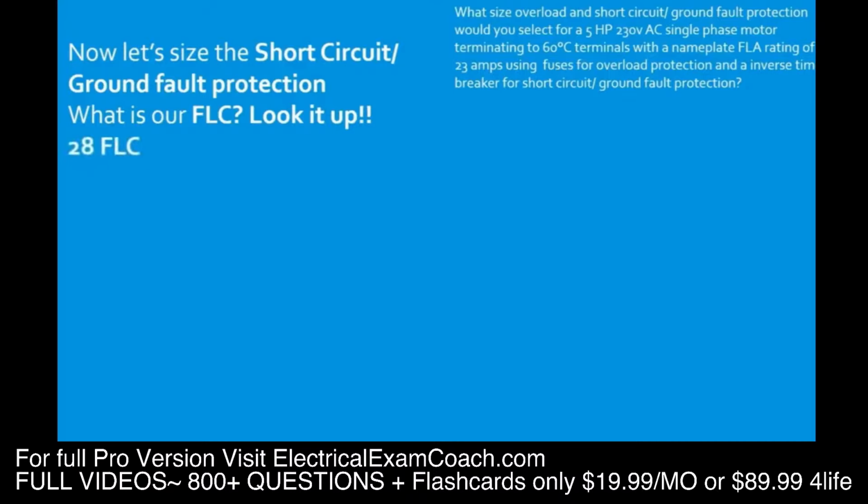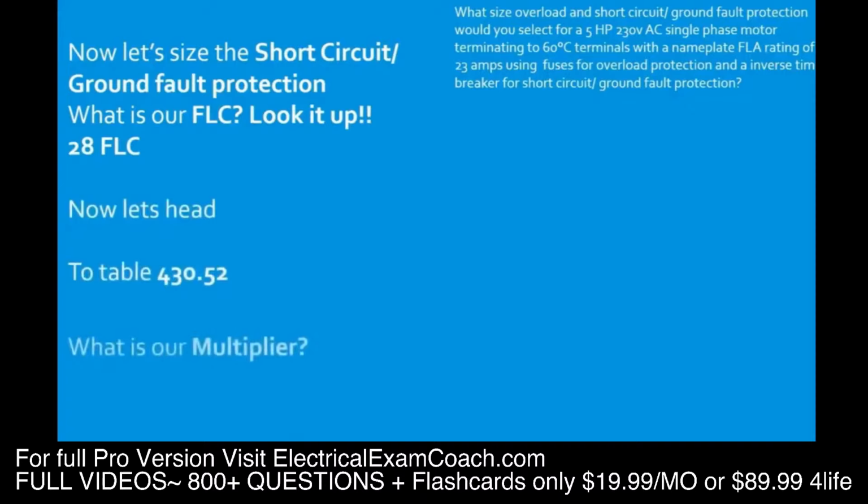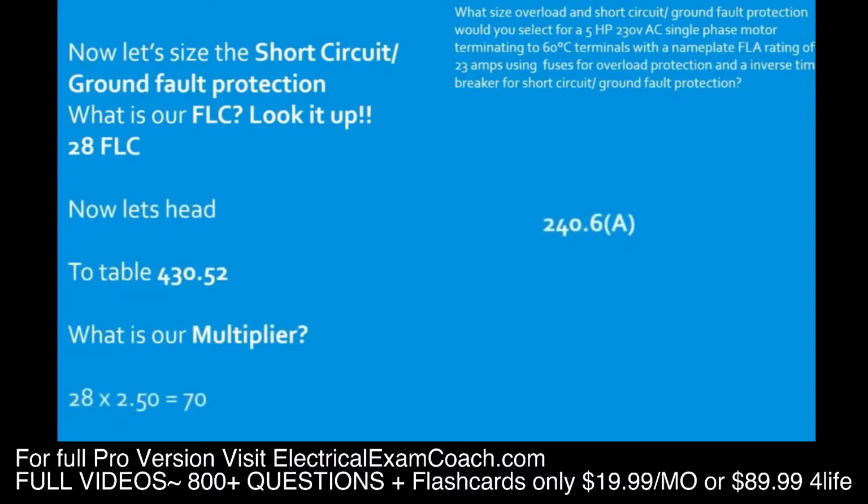We find that our FLC is 28. Now let's head to table 430.52. We're going to select our multiplier. We take 28 multiplied by 2.50. That's going to give us 70. We head to 240.6(A). We select the next size up, and it's going to give us a 25 amp overload on a 70 amp short circuit ground fault protection.